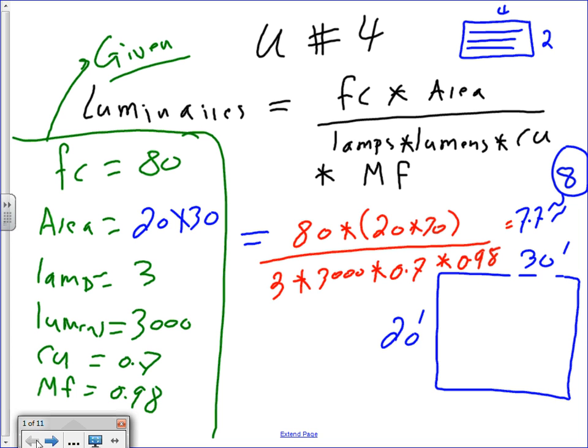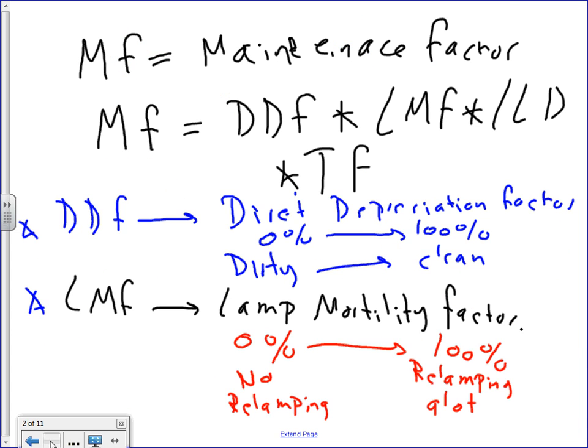If I ask you right now, Kerry, my friend, what is the foot candle right at this point here? Can you tell me? No. But you can tell me the foot candle average is 80. If I ask you what's the brightest point in this room, can you tell me from the average method? No. It can't tell you the brightest and the dimmest point. It only tells you the average. That's why they call it the lumen method, average, poor man's work. Though it's easy. Now let's go to the rich man's work.